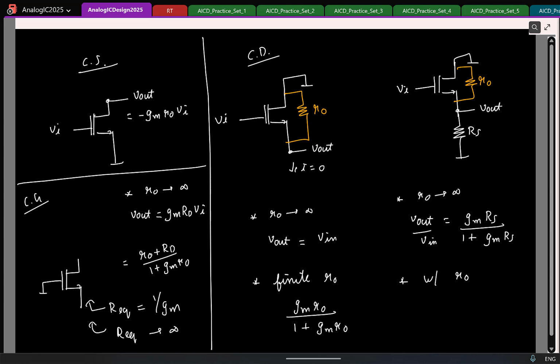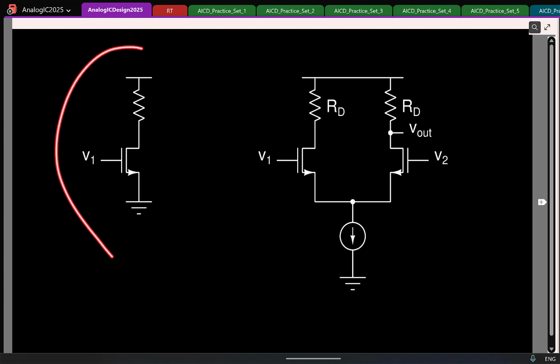Okay. So basically, as we know, among these three, which is a better amplifier? Common source. Why not common gate? Common gate also is giving some gain. Looking in impedance where? Yeah, I mean, for a good voltage amplifier, you want to have the input impedance to be how much? You want to make sure the entire voltage is sensed across the amplifier. Here the looking in resistance you see is really small, unless you put an open circuit here, but that is not practical. So that's why we prefer this. And so we started with this and then made a differential amplifier.